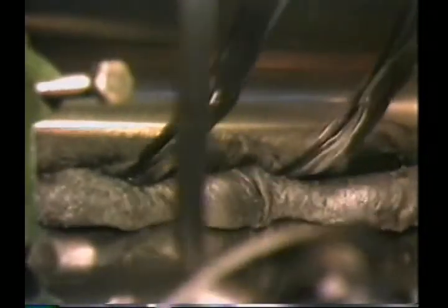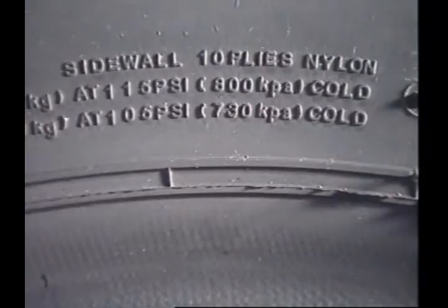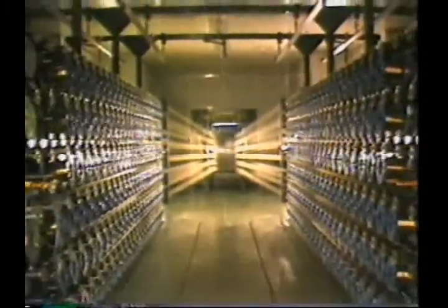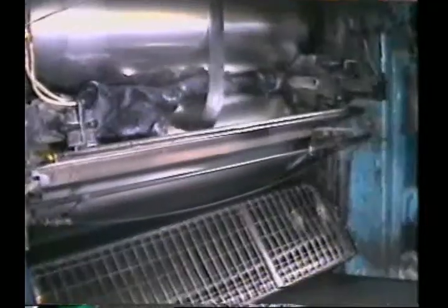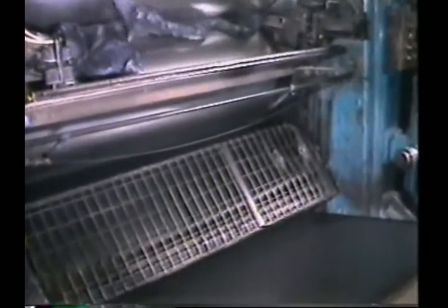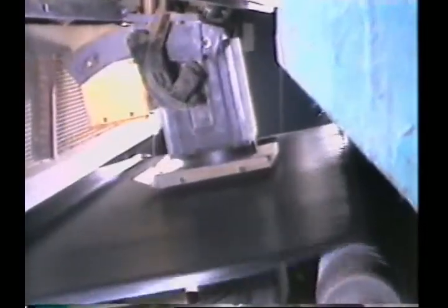The plies are made from cords of fabric coated with rubber. Early tires used cords of cotton, but with increased vehicle speeds and loads, rayon and nylon cords are now common. Cords of synthetic fabric have high tensile strength. They resist stretching, but are flexible under load. The cords are placed in parallel and impregnated with rubber to form sheets called plies. Plies have high strength in one direction and are flexible in other directions.